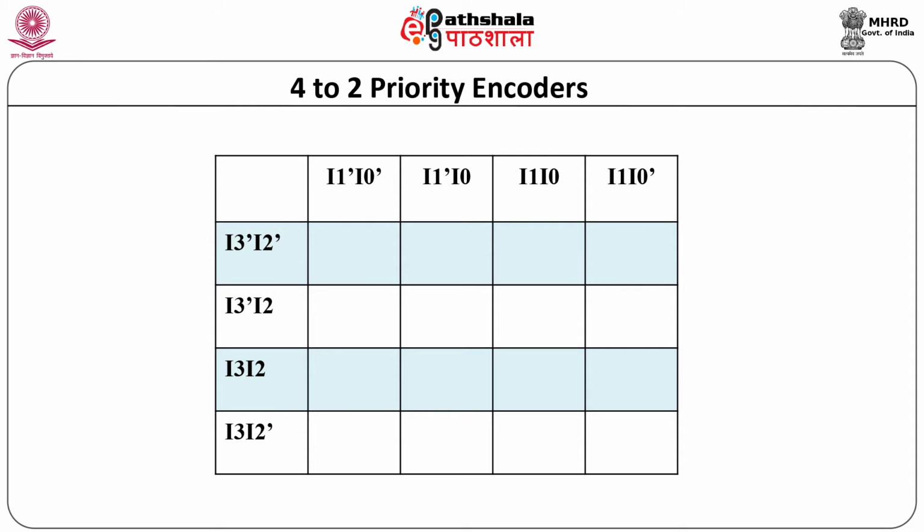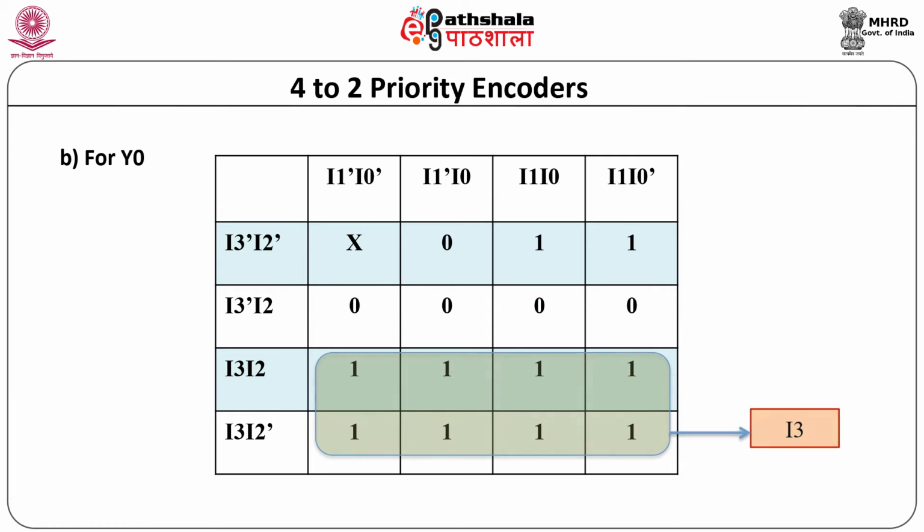Let us now prepare a K-map for output Y0. All the output values are placed for each possible input. The logic 1 is mapped for each output for all input conditions. For output Y0, it is possible to group 8 neighboring cells to form the octet. The octet provides only I3 by visual inspection and eliminates 3 variables.